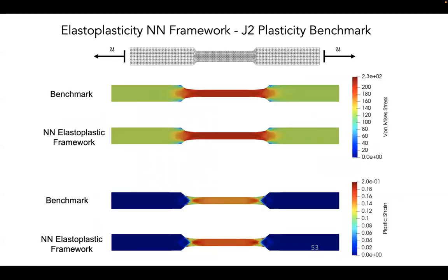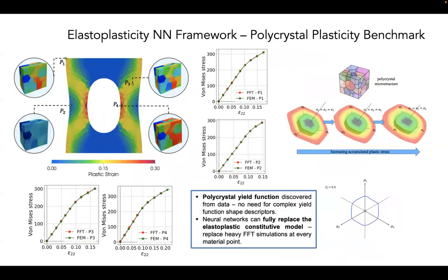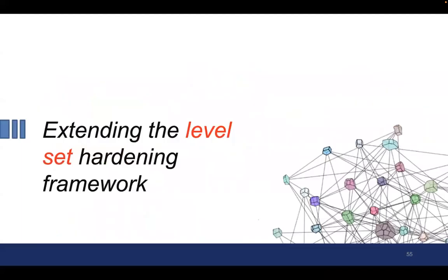You can actually use it for multi-scale simulation. This is a bar with some polycrystal plasticity, and you can see that it's very close to real multi-scale simulations. You can also use this to customize the constitutive law for a particular polycrystal. Usually you don't design a yield surface for a particular polycrystal, just because of the labor cost. But if this thing is automatic, you can have an image-direct-to-constitutive-law approach. If you can obtain the image of the polycrystal and run a lot of simulations, you can create a custom polycrystal in any different locations, then you can capture more results.